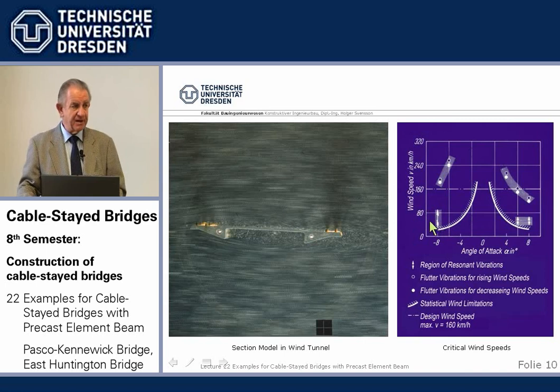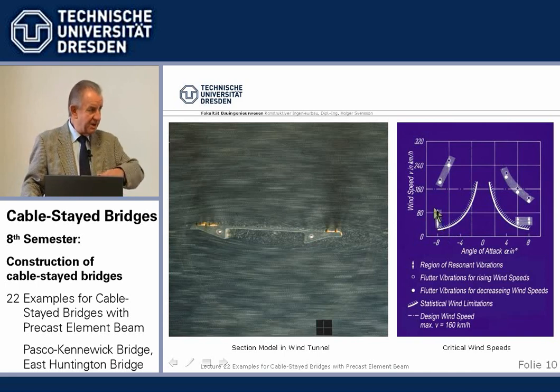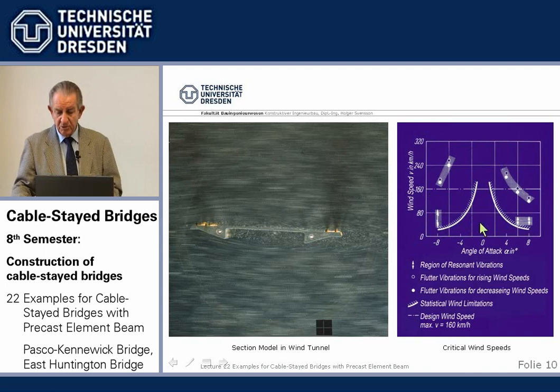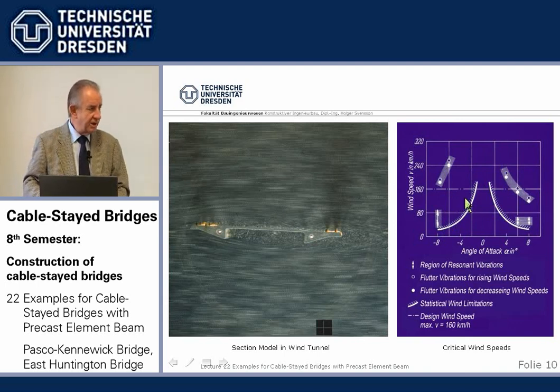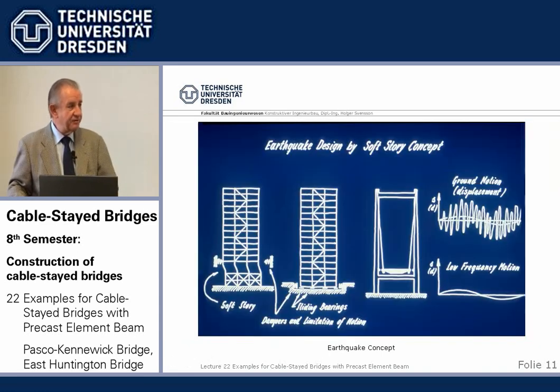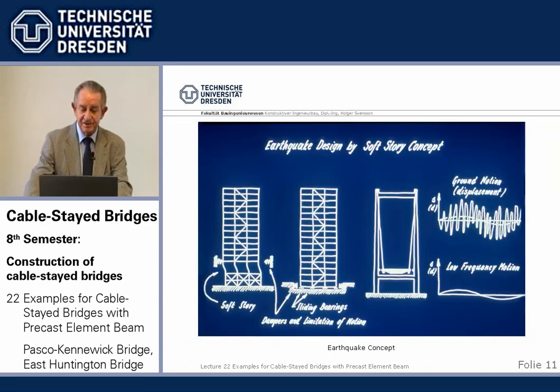And then the other is vortex shedding, which traditionally occurs at low wind speeds, but although it occurred at low wind speeds, it was beyond the wind limit because it occurred only at steep inclinations of 8 degrees. So with this picture, we could convince everybody, who, not knowing anything about aerodynamic stability, just by showing, look, all these phenomena are outside our limits, tick it off, well done. So that was how we convinced our client that this is safe.